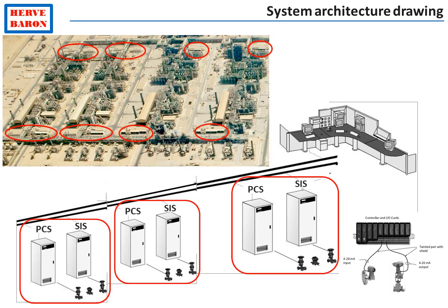Each of these systems, the process control system and the process safety system or safety instrumented system, comprises field instruments, controllers, as well as operator consoles. In order to minimize the cable lengths between field instruments and controllers, these controllers are located next to the units in instrumentation equipment rooms.